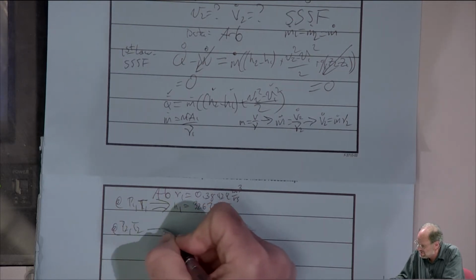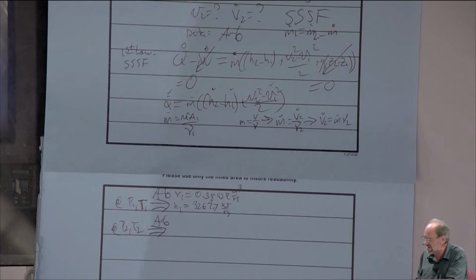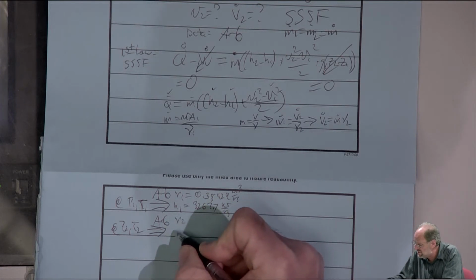And we'll do the same thing at point 2. At P2, T2, once again, we can do our little test. We will find that it is indeed still superheated. So we need v2 and h2.